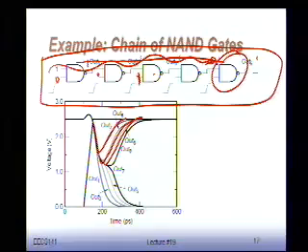Now, what's the way to get around this? Well, the way to get around this is to avoid having any gate in the system where you have very big differentiation between input arrival times. Now remember, we have done exactly this type of thing. Remember the carry select adder that we talked about a while back? And how we could make it logarithmic, not square root of n.